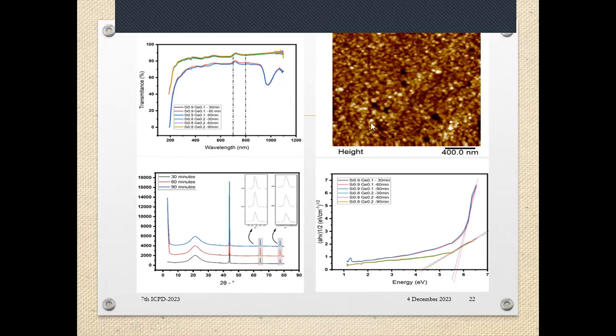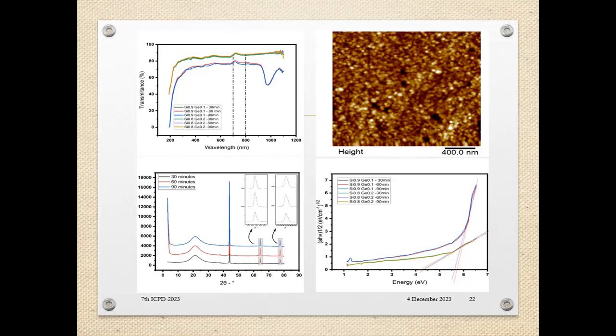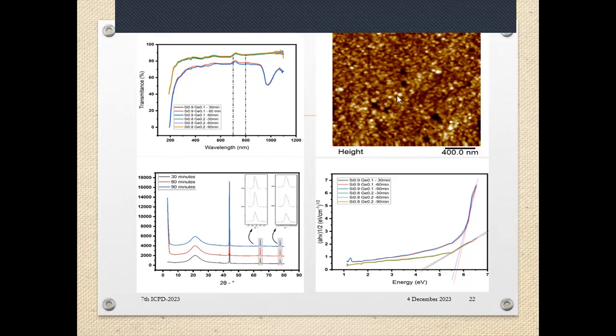We realized that it is nanocrystalline, and that is also cross-assessed by the XRD of the diverse nanocrystalline orientations, and also the absorption material. So it eventually proved that the silicon germanium we developed as a nanostructure on ITO glass substrate is nanocrystalline material with a higher band gap. That's why it is transparent, and its orientation of the small grain crystals is diverse. That can be realized from AFM and XRD analysis.